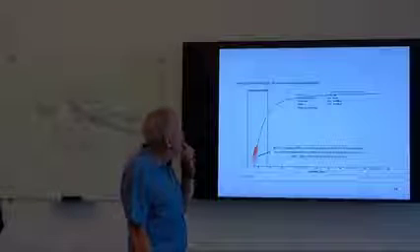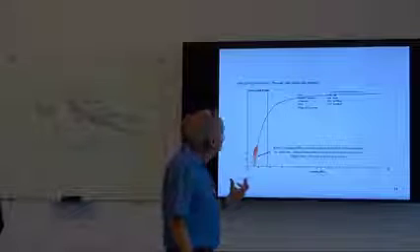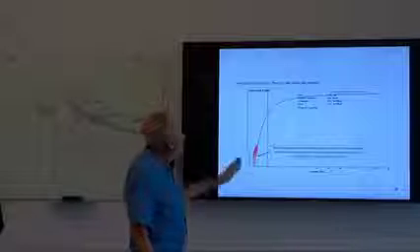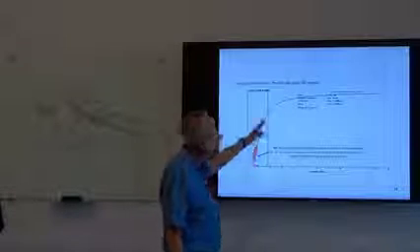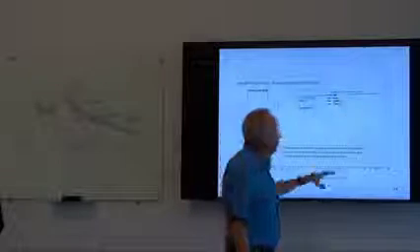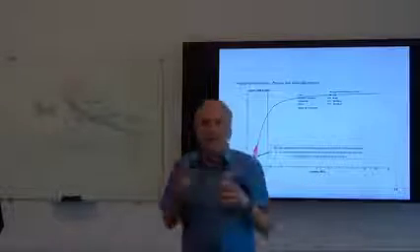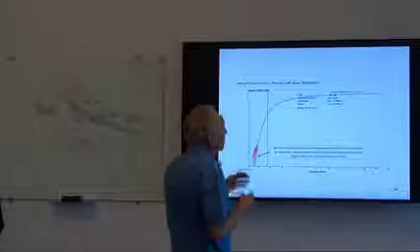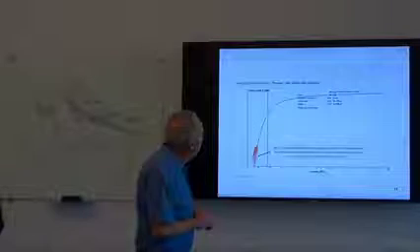We're in that sort of 200 to 300 barrels per million range, and free-flowing conditions, let's say, or at least that's what's modeled here. We see very low gas velocity down deep in the well, and then it sort of breaks over as it comes to surface, and this gas comes out of solution, and the gas expands due to the pressure difference, and we have a very high gas velocity towards surface.